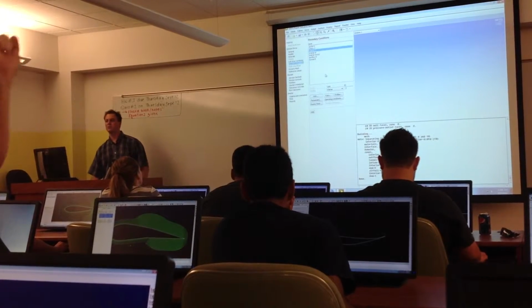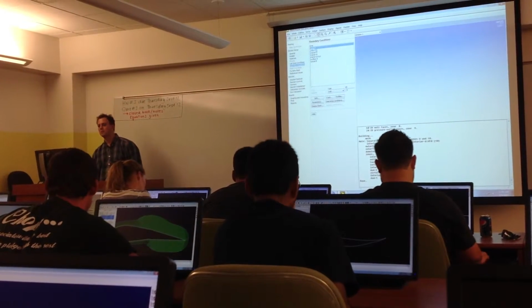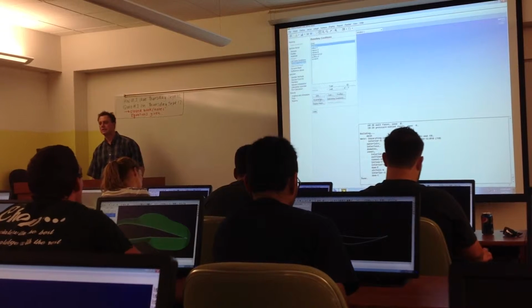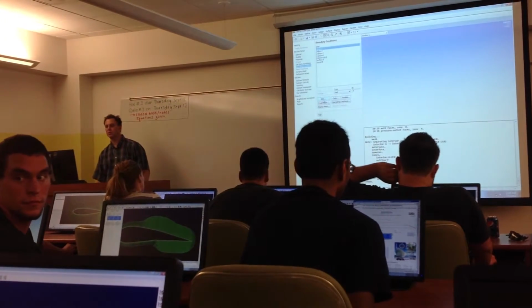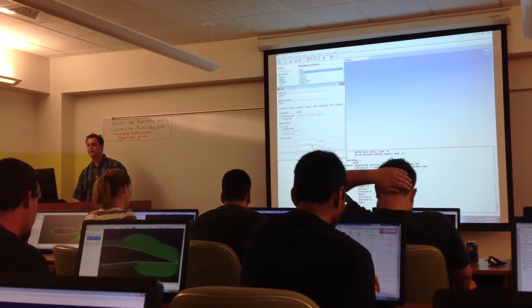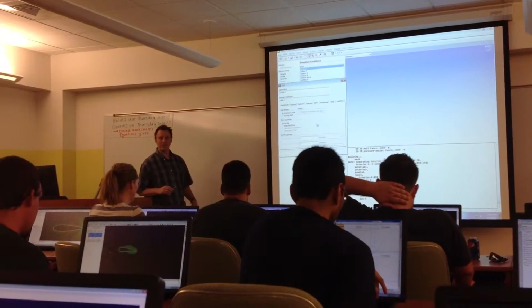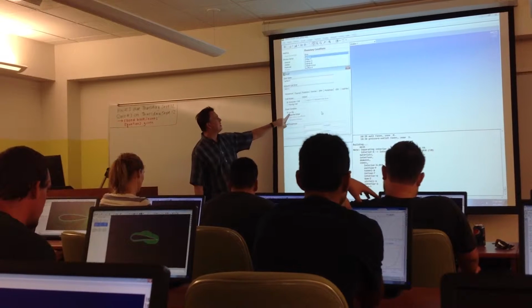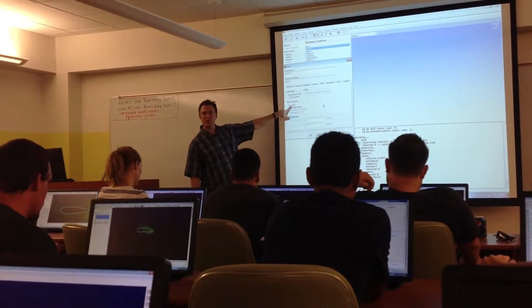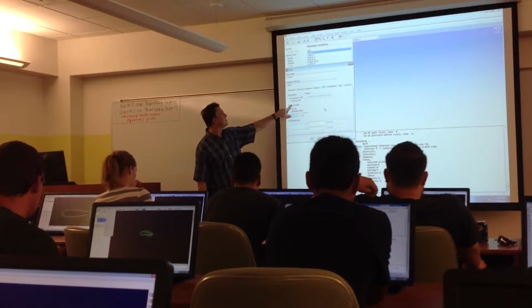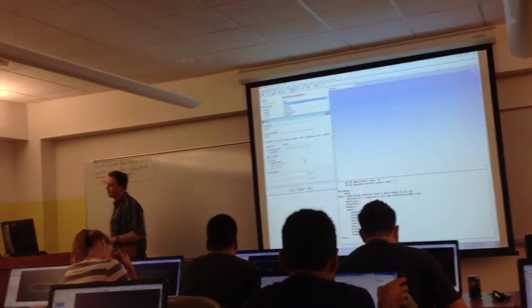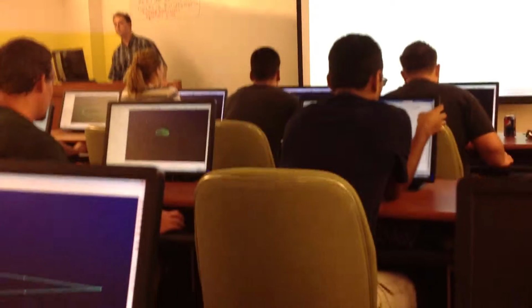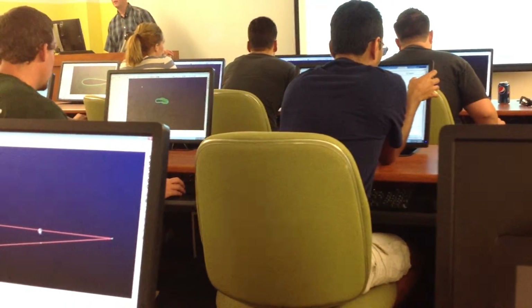Boundary conditions is the first thing you need to modify. Go to the airfoil, for example, the first one on the list. And in this case, it may actually be the default. I go under edit and see what specifically it's got set. It's got no-slip shear conditions set, which is what we want for the airfoil. Stationary wall, so it's not a turbomachinery or something that's rotating. So leave it alone. Default is fine.